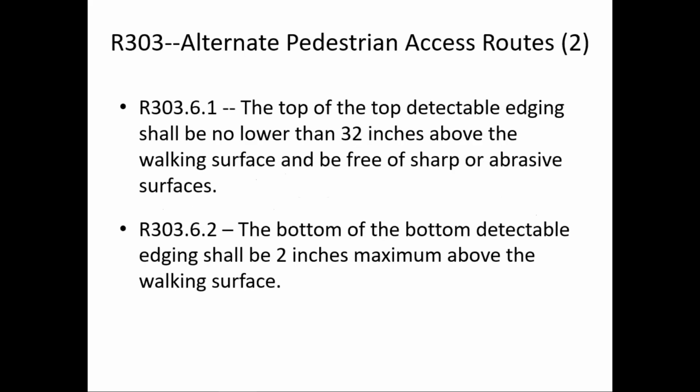And here's what section R303.6 specifically talks about in terms of this detectable edging. It says the top of the detectable edging shall be no lower than 32 inches above the walking surface and be free of sharp or abrasive surfaces.